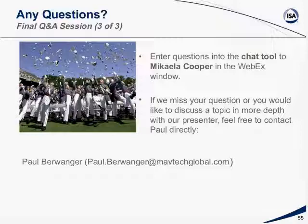Well, typically, after the alarm philosophy, you haven't done anything yet. You've just established the framework for going forward. And so you'll start seeing benefits first after you've done the bad actor analysis and have done the implementation on that. You'll see immediate benefits with that. And then after the rationalization, you'll see benefits as well. Developing the alarm philosophy just tells you what good looks like, how you've defined what success will be. It's really after the bad actor analysis and during the alarm management process that you actually get benefits, and you can see how well the system performs compared to what we've established as success in the alarm philosophy.